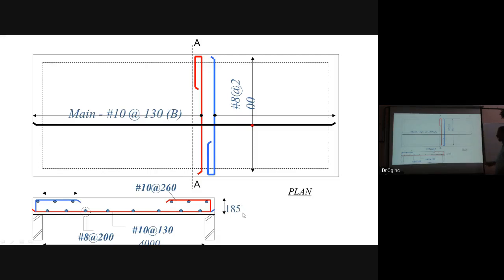See, you can find out this is 180 millimeter thick overall depth. Now from here to here is the effective depth. From here to here, from the top, top layer to here, this is the effective depth. From the top layer to the bottom layer, all the way here, that is the overall depth of the slab. Is it not? And this is how we prepare it with reinforcement.